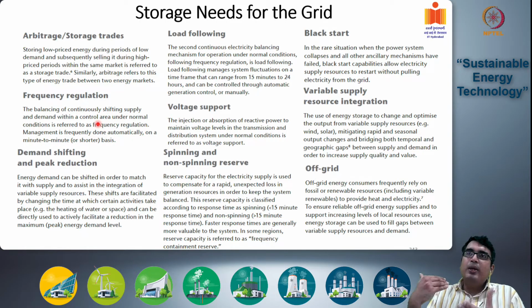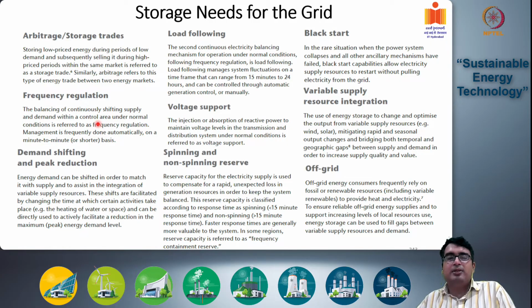So this quick injection and absorption of electricity from the grid is also an important aspect of storage technology. And this is called frequency regulation, and as you can understand, this type of storage system does not need long periods, but it has to be fast response, low capacity but high efficiency systems.